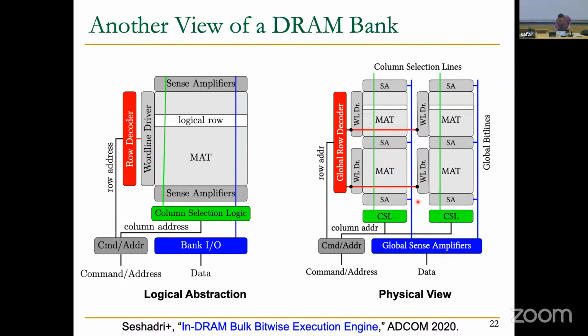So what are global bit lines? You have seen the row buffer already. You have to take data out from the row buffer to the chip interface. In between, on that path, you have what's called global sense amplifiers. These are still operating similarly to your row buffers, but smaller in the sense that you have fewer of these.